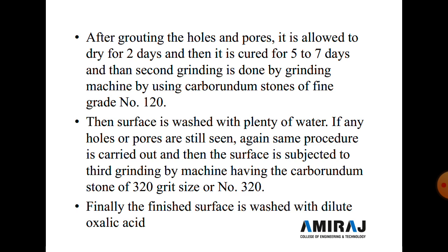Now after grouting the holes and pores, it is allowed to dry for 2 days, and then it is cured for 5 to 7 days, and then second grinding is done by the grinding machine. Use the carborundum stone of a fine grade, number 120, and then the surface is washed with water. If the holes or pores are still seen, the same procedure is carried out again, and then the surface is